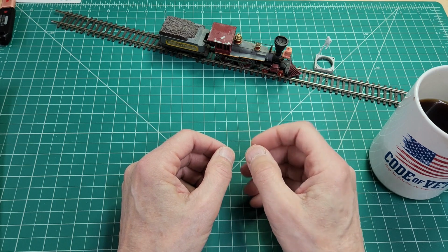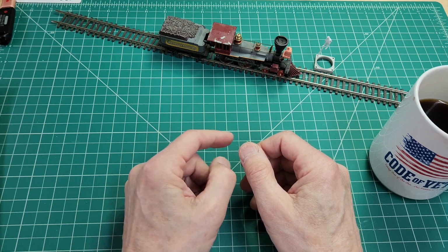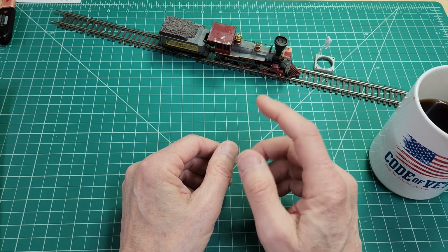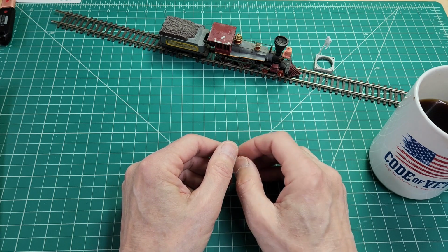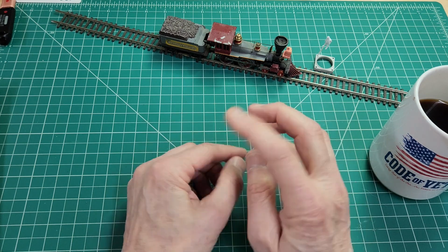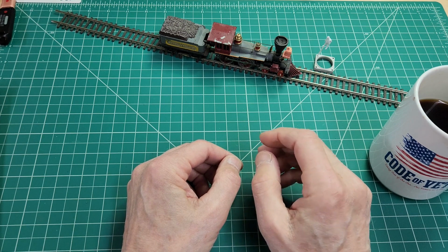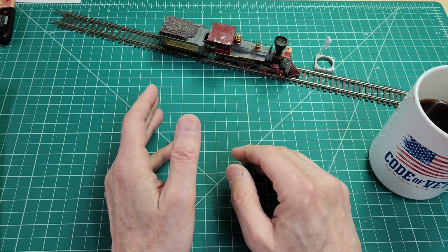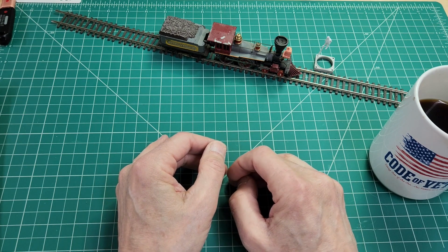So creating an object of a driver class is required for using this library. But why, you might ask? Well, the object pointer in the devconfig array is used by the library to make a callback to that driver's init method. So, when it calls attempt config at the time that the device is detected, this callback takes place.